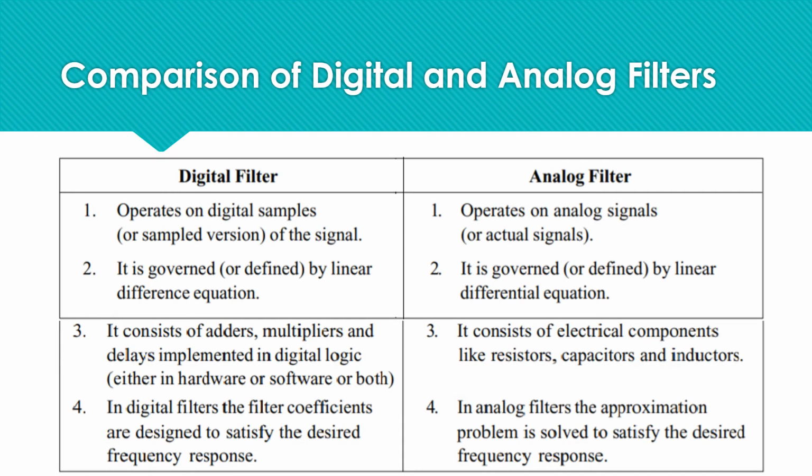Comparison of digital and analog filters. Digital filters operate on digital samples of the signal, whereas analog filters operate on analog signals. Digital filter is governed by a linear difference equation, whereas analog is governed by a linear differential equation.